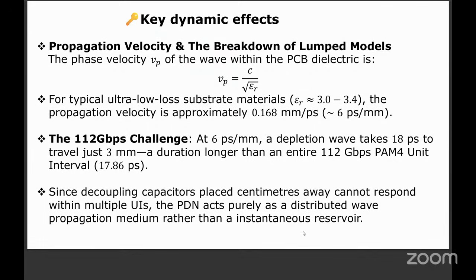A decoupling capacitor placed centimeters away cannot respond within multiple unit intervals. The PDN acts purely as a distributed wave propagation medium rather than an instantaneous reservoir. The power must be available at a distance and at a time. Otherwise, it is useless. Next page, please.